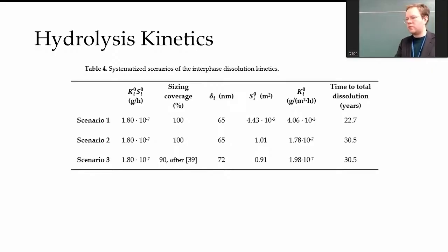Individually, we have to include this information, let's say maybe in finite elements, to have the geometry. But people realize, like with frozen water and melted water, that there is an intensifier. Typically here, the higher the temperature, the faster the reaction with the Arrhenius approach. But if it is frozen, there's the freeze-thaw. So if it goes around 0 degrees, it's another process which is not included here, but it affects and mechanically damages the material, if it is the ice that is being built inside.